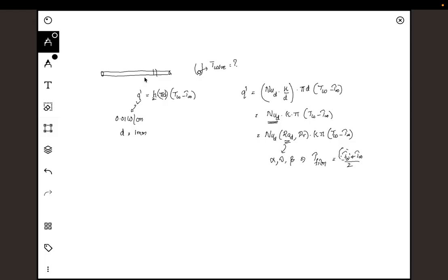So you have to assume a given value of TW, compute all the properties. So assume TW, get the properties and compute Ra, Prandtl number, etc. And from them use Nu, get q, and once you have the q, you can substitute that back again to see if this is matching with your given value of 0.01.